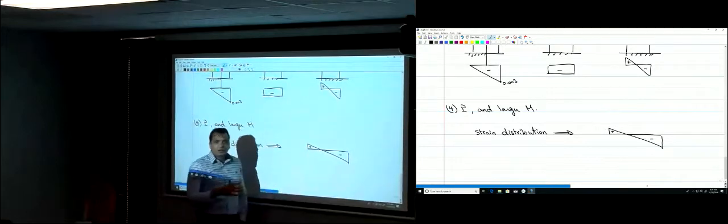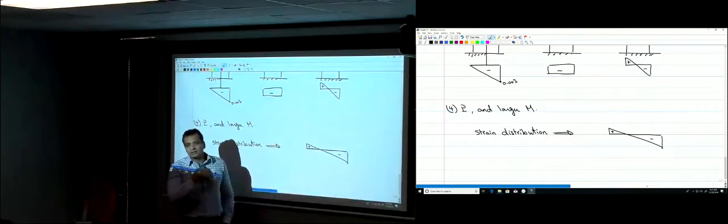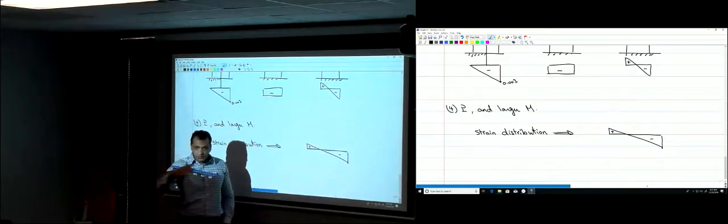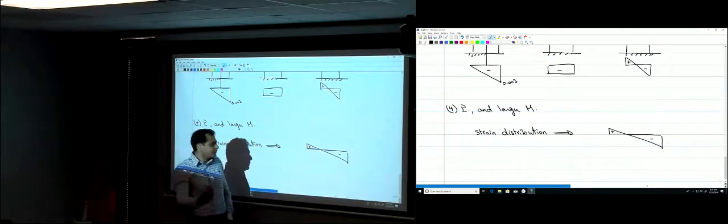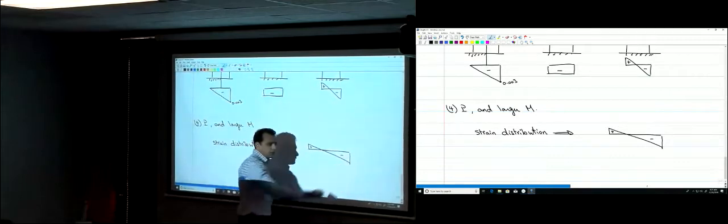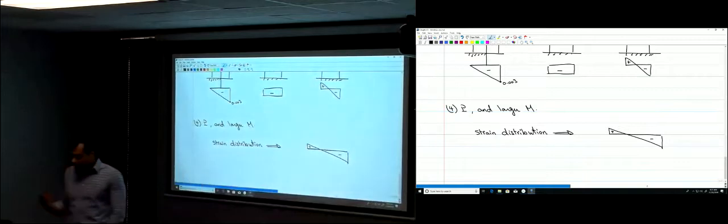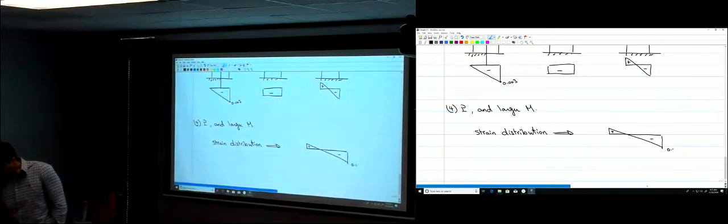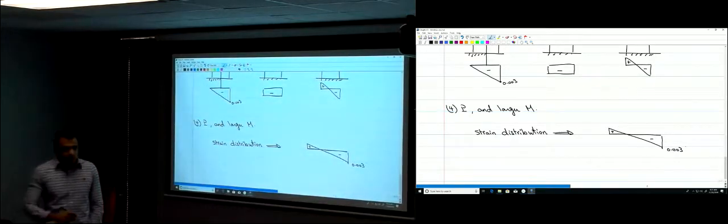And the steel, the strain can go beyond yielding, right? And I can still depend on it. So actually what controls the failure of the column over here is the compression strain here. So again, it will fail when this is 0.003, okay?